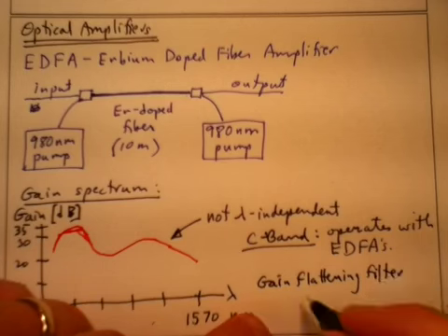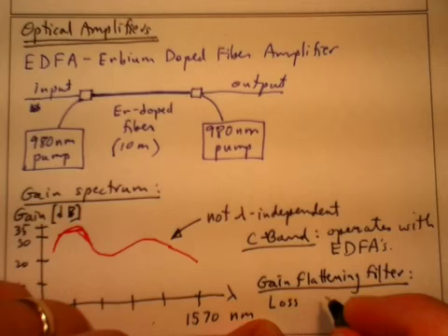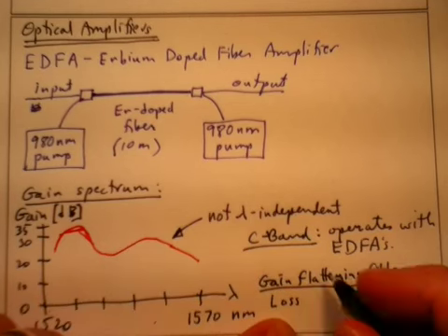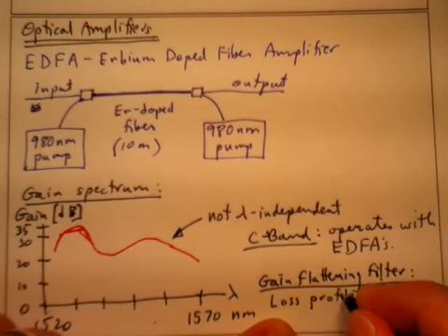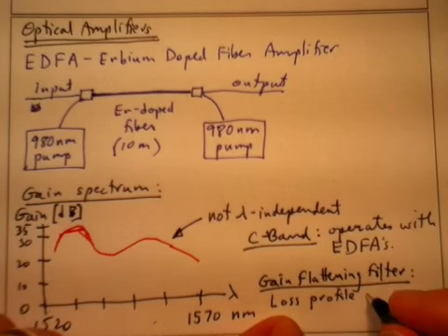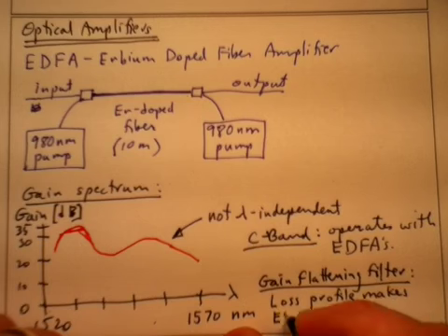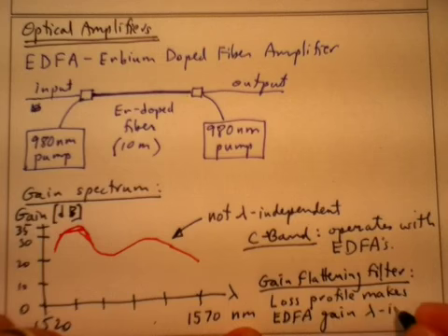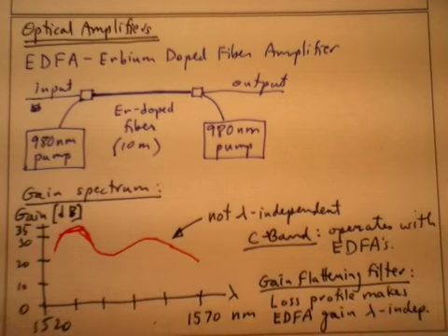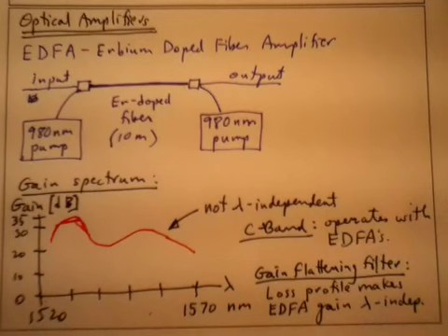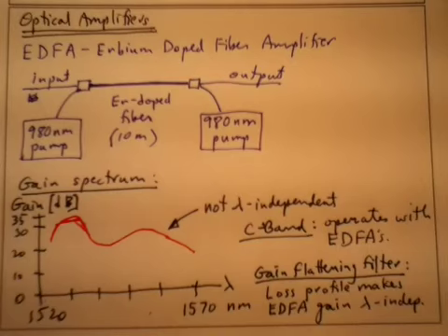It has a loss profile complementary to that of the gain spectrum, and makes the EDFA gain lambda independent. And that's an important thing because, as I'll show you in the next video, we really do want all of our optical channels to have the same power in a WDM system. And I'll come back in the next video and continue from there. Thanks.